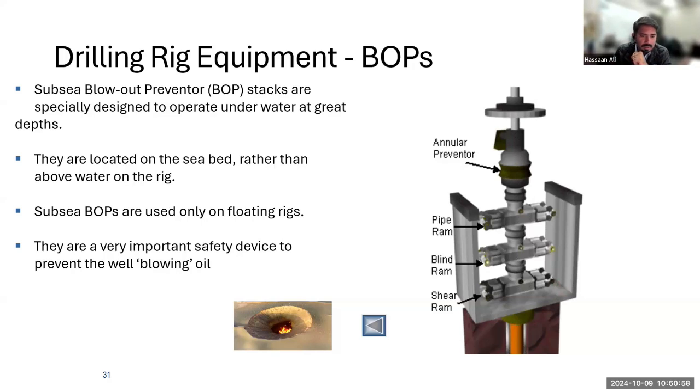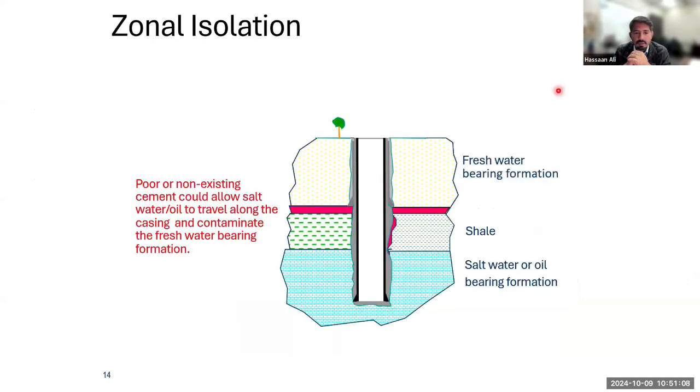So common challenges that can be faced with the cementing operation is, let's go to this one. The common one is getting your slurry to the right density and making sure that it has certain characteristics. It's a recipe, right? You have to mix certain things at certain times in a certain quantity, so you get that property or that specification downhole. So usually a lot of lab testing is done on the surface to ensure that your cement has the right properties. Getting it to the right specification is very important. I think that is the first and foremost problem that is faced.